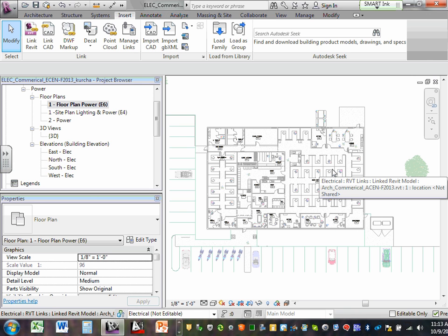Any file. When you bring them, guys, it always puts them as 2D, no 3D, and it will always slam them at 0 elevation. Here's mistake number one. You're not going to encounter it here, but next project, if you're looking at the second floor, would you be able to see them? No, they're coming in at 0 level. You wouldn't be able to see it.